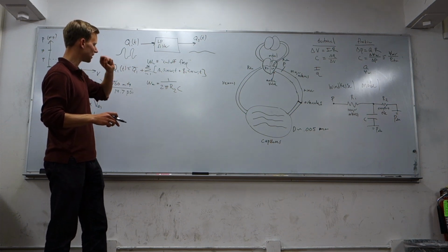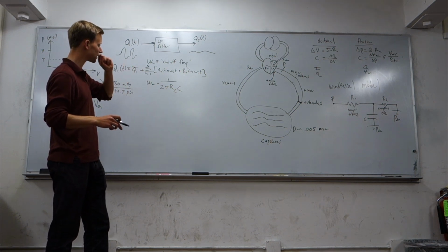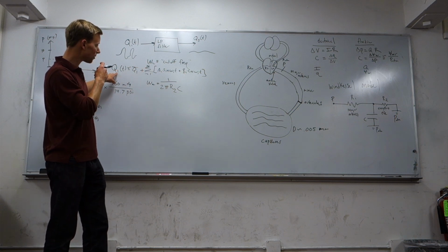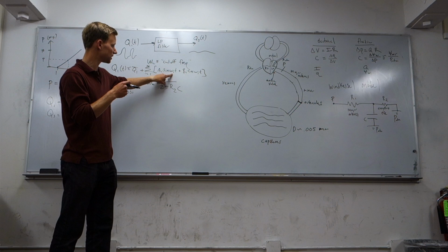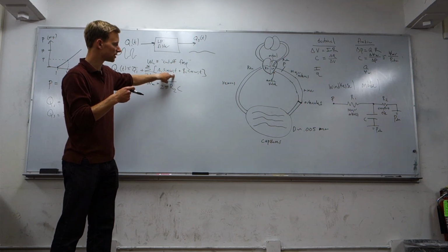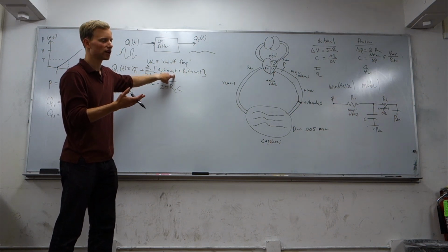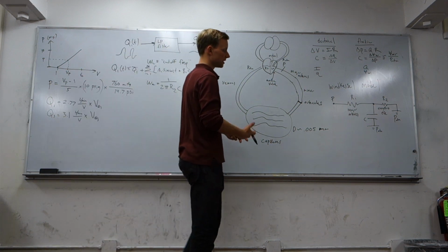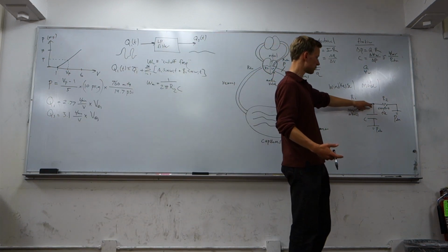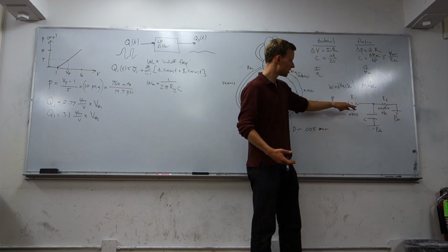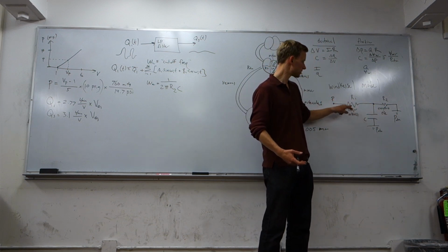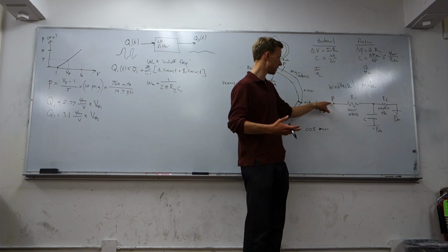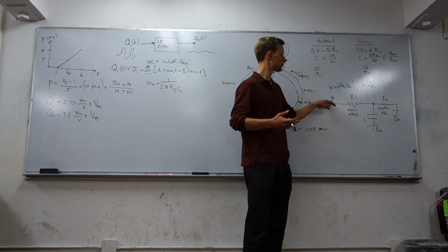So what we're going to do next is use the input Q1, decompose it into a bunch of sines and cosines with different frequencies, and use these as input signals to our ODE, which is the solution to our circuit equation. So what we can do is write Kirchhoff's current and voltage laws at each node, write the constitutive equation for each circuit element for the R's and C, and we can solve for what the pressure, or the potential, will be in the circuit at any point.